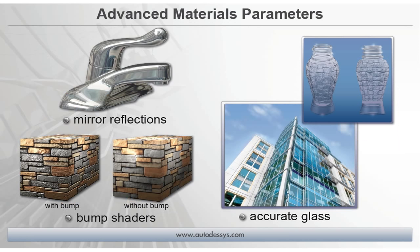Now, if you add the RenderZone plugin, then what do you get? You get more materials and more parameters, so you can do things that you cannot do with a traditional interactive shaded rendering mode. So you can do ray traced mirror type reflections. You can do bump shader effects. So you can see the stone on the right is just a flat image, and the image on the left is more of a 3D bump shader effect that can be ray traced. You can create accurate glass.